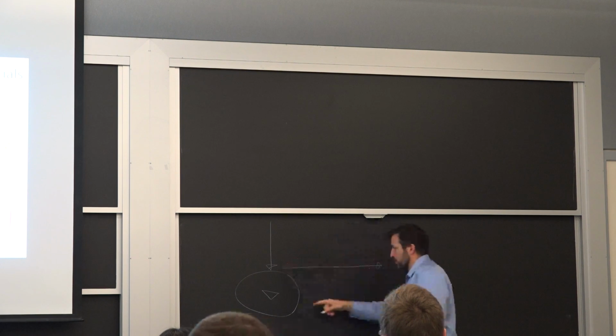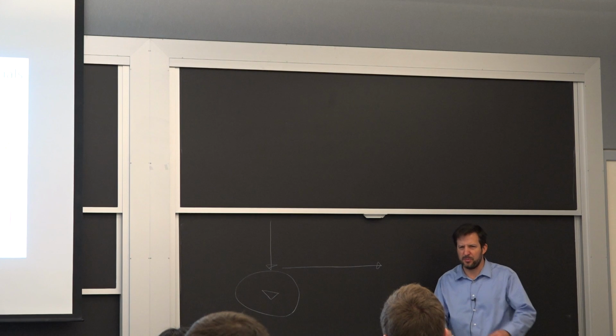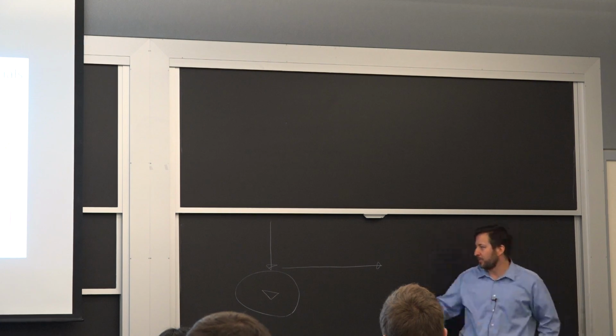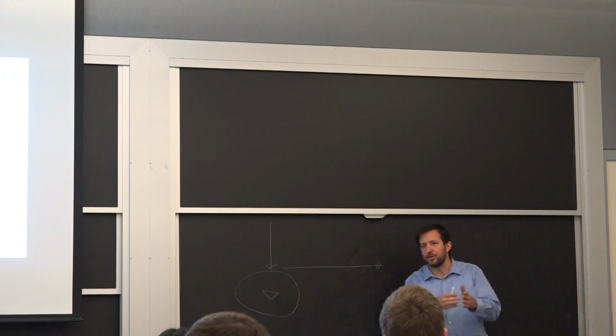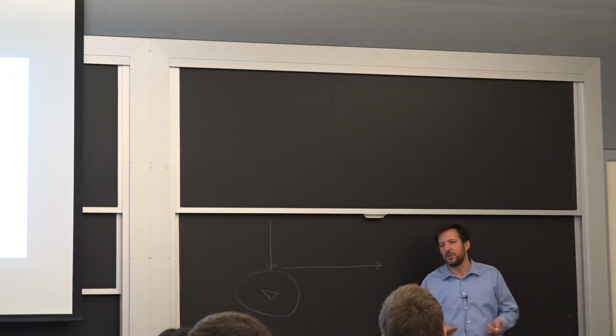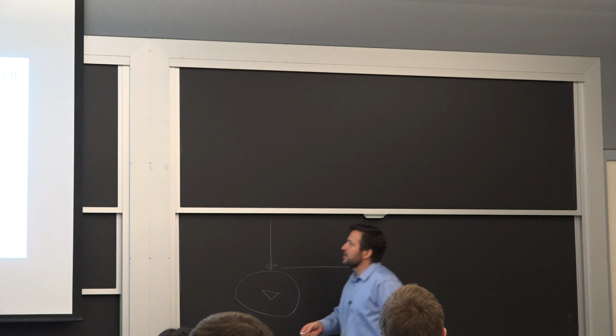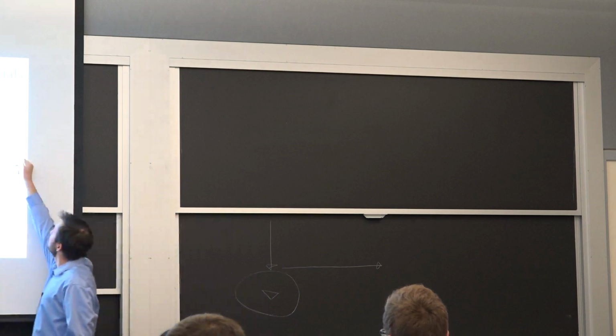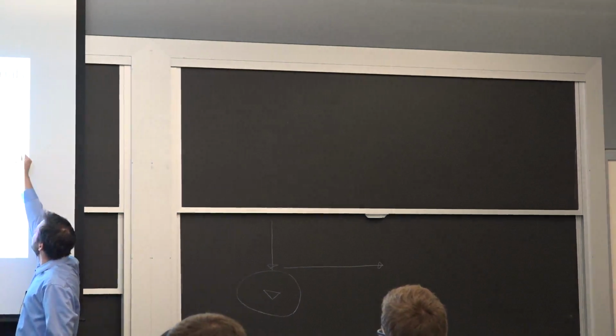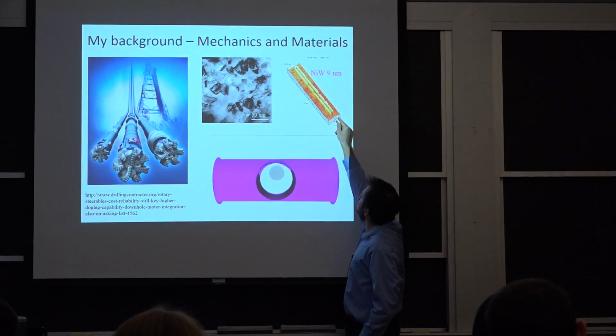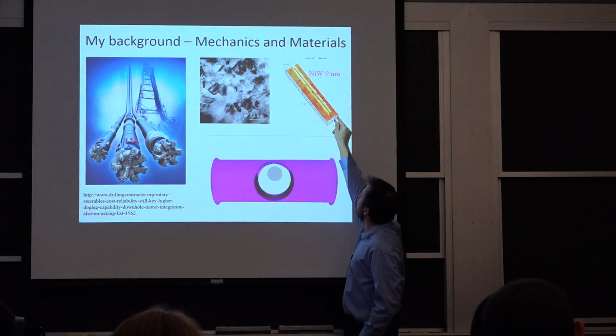And of course, we don't use a pyramid tip, it would be too hard to align, so we have cones and spheres as the 2 main geometries that we're using. And that profile here is essentially starting down, you see the hole. So when you indent, you actually go a little deeper because you don't have that pileup.